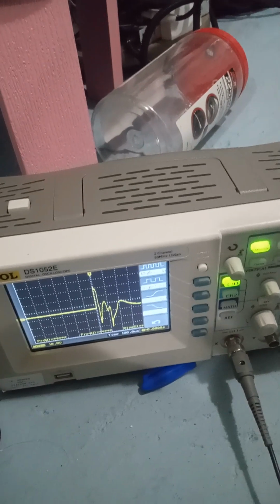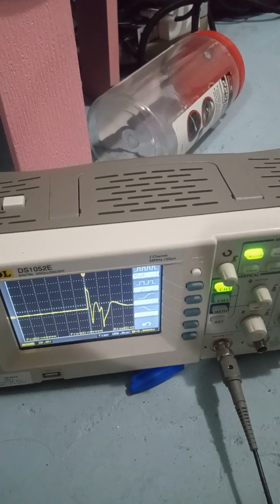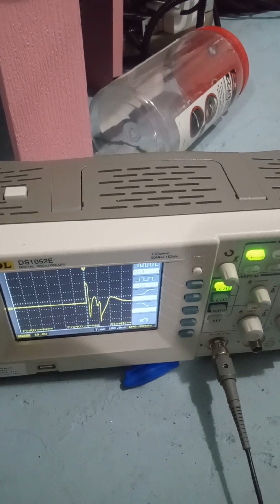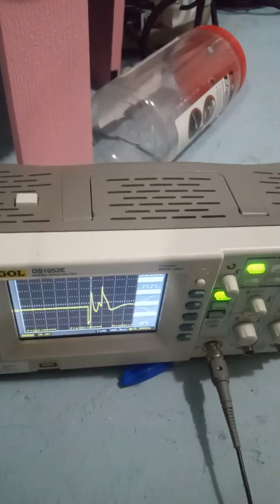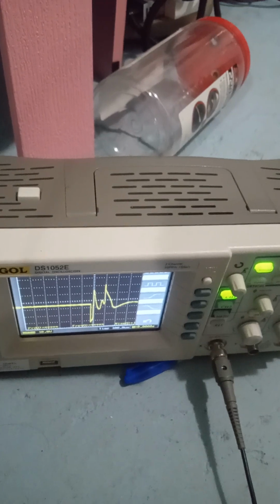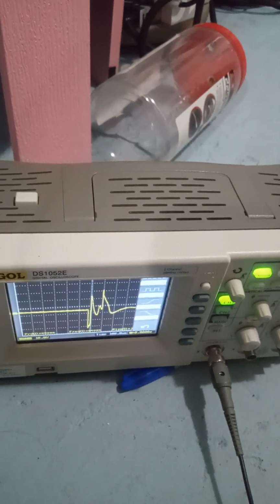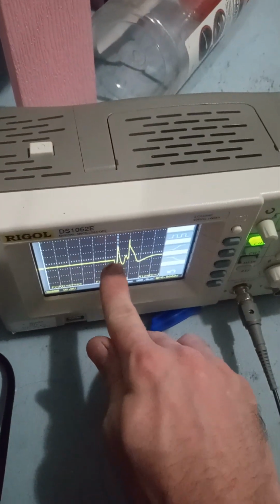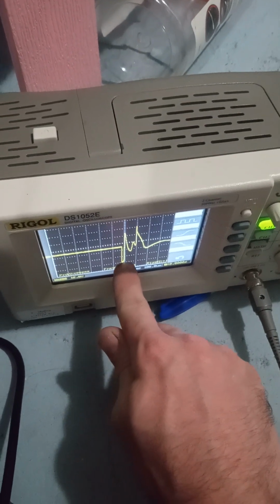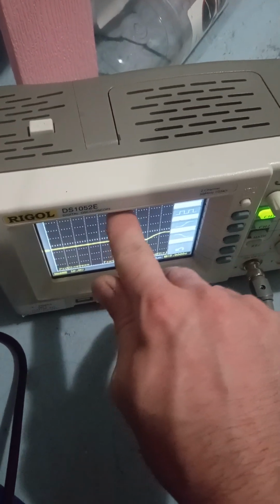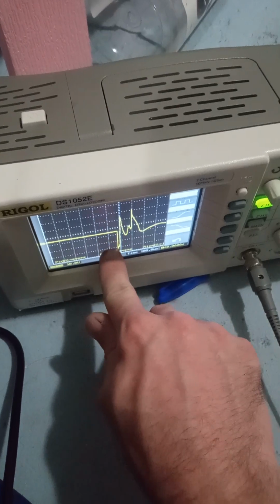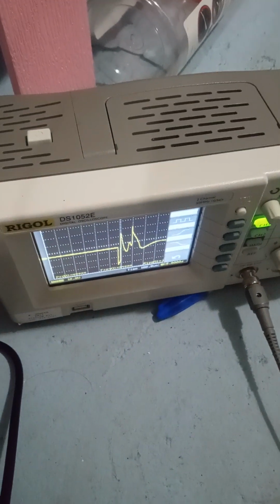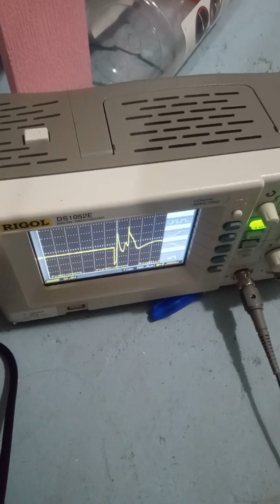So I'll do that real quick and give you guys an example of what off switching looks like. So this is on switching, and I'll show you what off switching looks like just by switching the polarity on the oscilloscope leads. And that's what off looks like on the GDT phase. So going across, you want on, off, off, on. And this right here, the first indicator, if it's pointing up like it was, that's on. If it's pointing down, then that's off. And that's how you phase your GDT for a full bridge for switching.